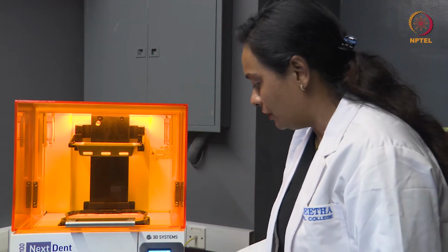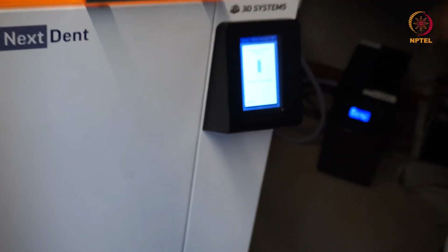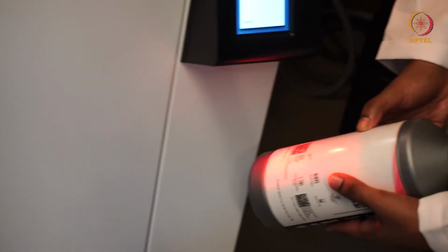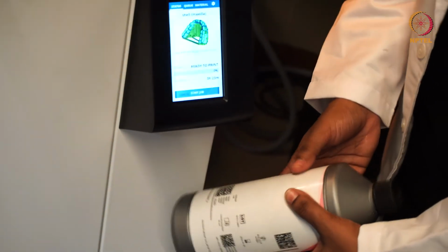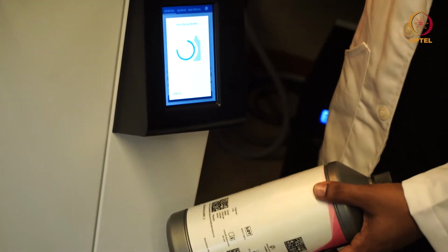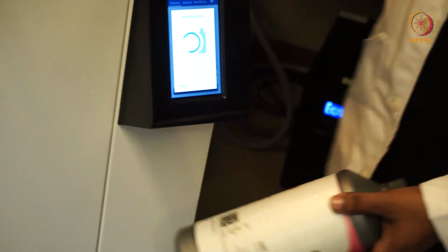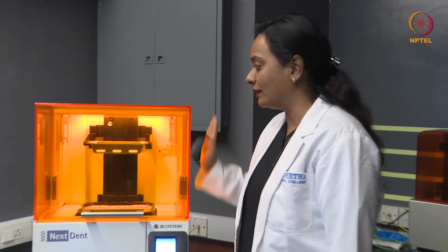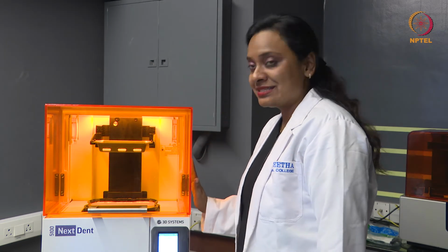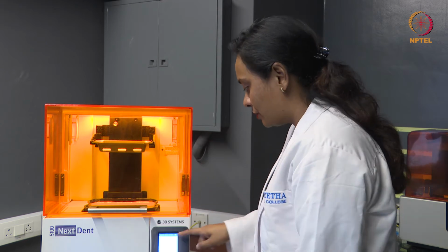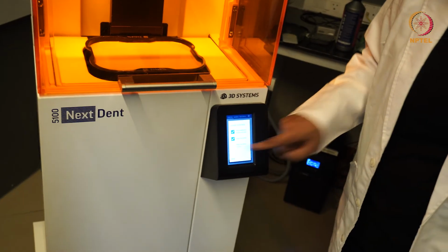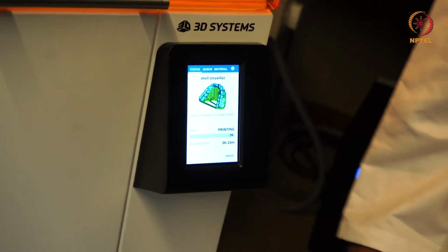So once this is uploaded, we start, and then the resin which we are using has to be scanned here. This is a foolproof system because any outdated or expired resin will not be accepted by the printer. So once the resin is identified, next we have to double check whether the platform is clean, the resin is stirred, and the printer is stable. So the print platform is empty and clean, the resin tray is full, and we have ensured the resin is completely stirred. So now we give start job, and in another 23 minutes you will see that the surgical guide will be ready, printed.